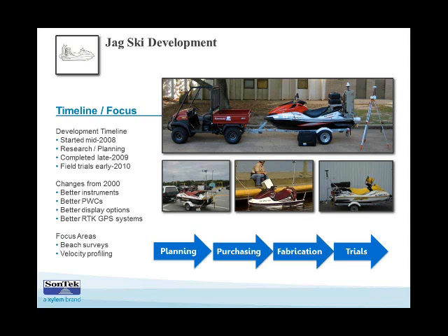So this plot here shows just some average velocities at surface, depth average, and at the bottom, and then some CTD cast locations where we're using the CastAway CTD for sound speed corrections, triangulated and contoured with the bathymetry map underneath it. So that's all just collected in River Surveyor Live, exported, and then processed after the fact.